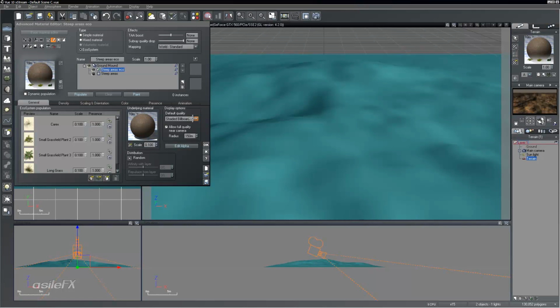Cache files created in the fixed hardware pipeline will not be usable within the shader 4 display, so then new cache files have to be generated. However, if you create your cache files with the shader 4 model, they can be used in the host application and in the standalone. No extra files need to be created, but they are a little bit bigger. They also have an impact on the amount of memory currently being used in the scene. So it's something you can keep an eye on to manage memory if needed.